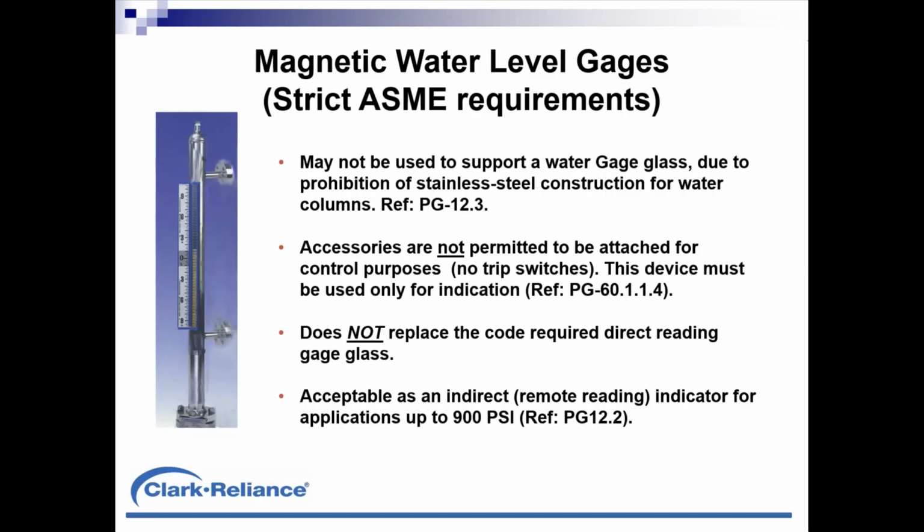If you are using any of these devices on a water application, be it feed water, condensate tank, or on a boiler application, we would recommend periodic inspection of those floats. Doesn't matter who's the manufacturer. There's typically a flanged access at the lower end of the unit. When that unit's opened up, you can remove the float.